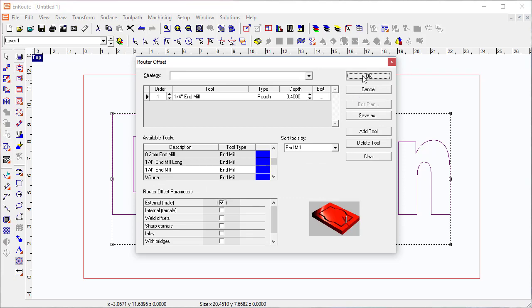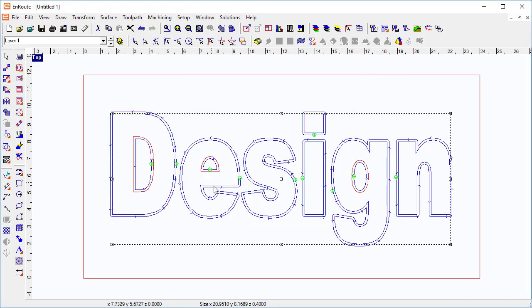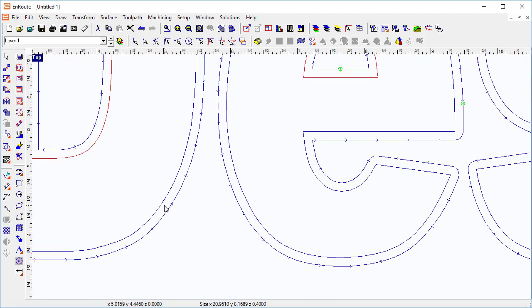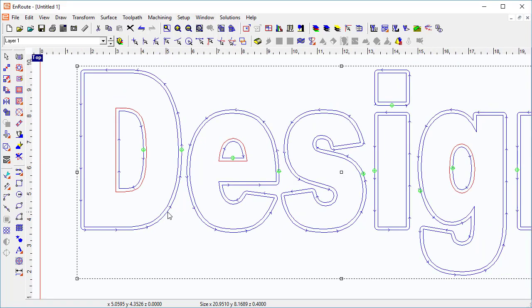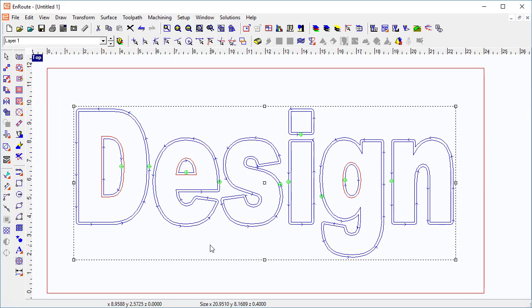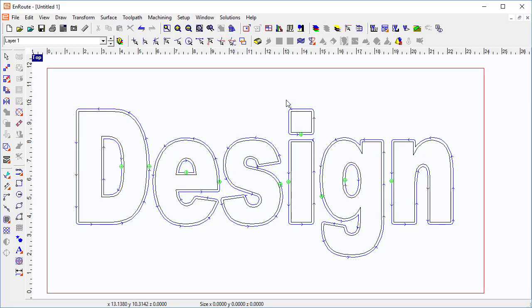how to edit the parameters. Okay, so I create the toolpaths, and you see the toolpaths here are offset from the geometry, of course based on the tool diameter, and so that's the way to identify the toolpaths. And start points are shown here. I could have added entry, exit. There's lots of things I can do with the toolpaths, but once I have them, then there's ways for me to visualize what they're going to look like.